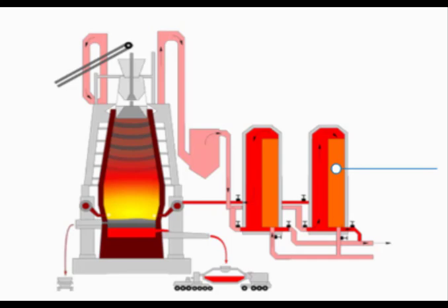It is quite common to have three or four stoves, so that at any time one stove is on blast while the others are on gas. A stove that is boxed, or on gas, has been heated up to temperature and sealed so that it is ready to go on blast. If one stove is down for repair, it is possible to use the other two. So that's the reason we will have almost three to four stoves. If one stove is to be repaired, we use the others. So this is how the stove works.